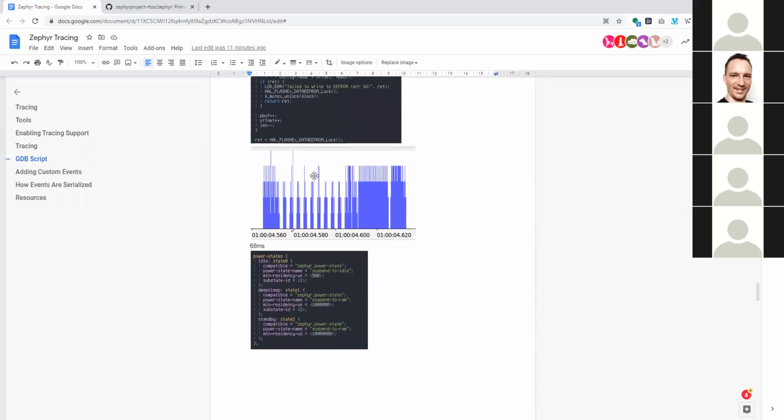And here's another trace. Here I have actually switched this application to use SPI interrupt driven mode. So in this case, we are actually seeing SPI interrupts happening. Because we are tracing ISR enter and ISR exit, we can see every single SPI interrupt.